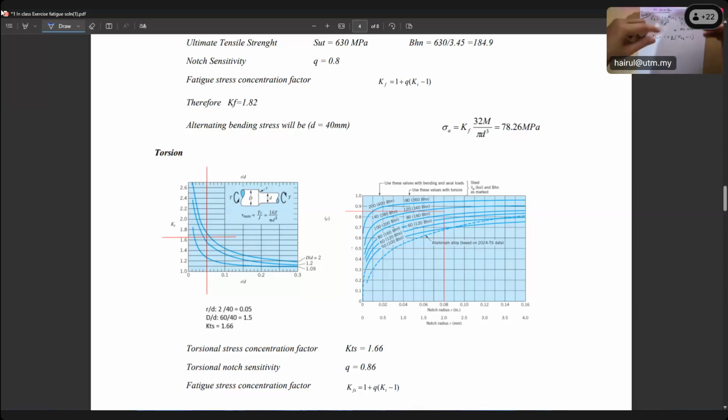It means for the bending stress, you take the maximum case where you have a notch, where the stress is more concentrated compared to pure bending. Pure bending is like this, normal, but when you have a notch, you need to multiply. So your sigma bending is KF bending times your 43, the nominal sigma bending from before, which we did not multiply. Your sigma bending must be multiplied by KF bending.